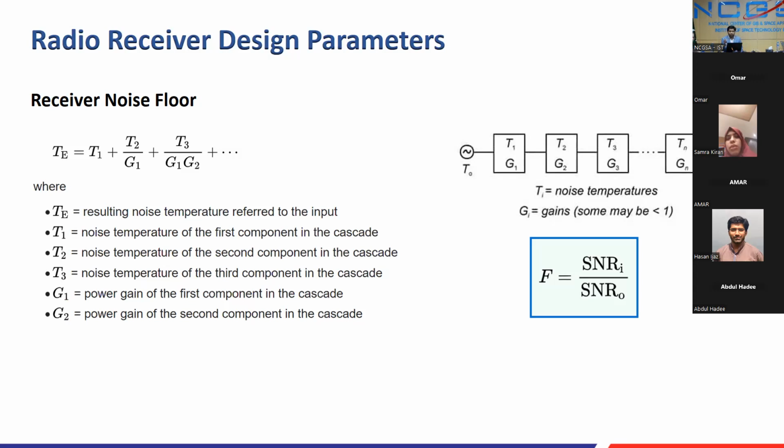The natural noise floor: you can filter out the unwanted signals in the ambient environment. I have already shared with you, if you are working within the band of 100 megahertz to 1 gigahertz, there are a lot of other frequencies around in the ambient environment. I've shared TV signals, GSM signals, VHF radio signals, VHF walkie-talkie signals, VHF SDR signals, HF radio signals, HAM radio signals, then open 433 megahertz ISM band signals. So there's a lot going on in that environment. But as you get those signals into your receiver via your antenna, the first thing they will see is the electronic noise contributed by your own receiver. That you cannot lower. That is driven by the temperature of the system. If you move to higher temperatures, your noise figure will degrade. If you have a proper cooling mechanism, then your noise figure will be stable.